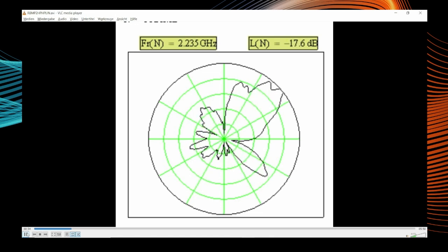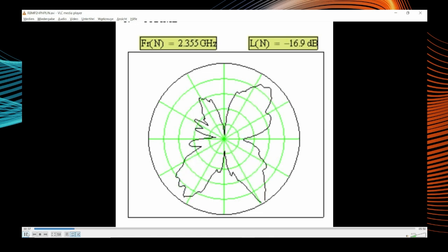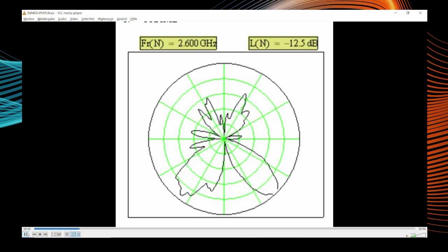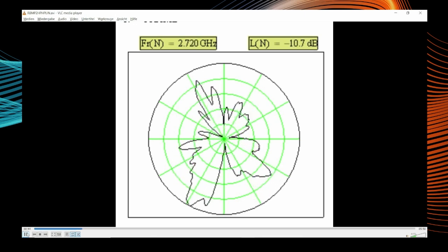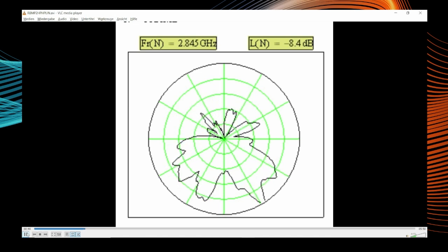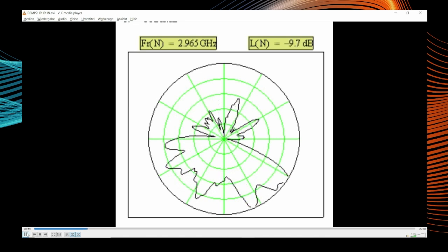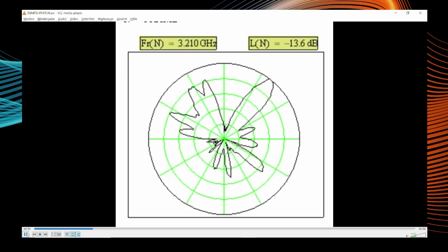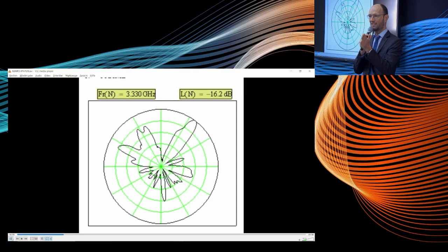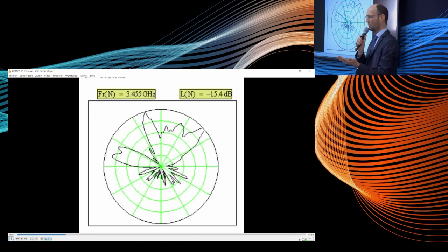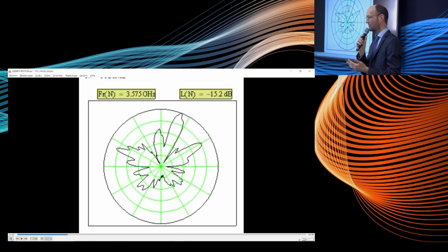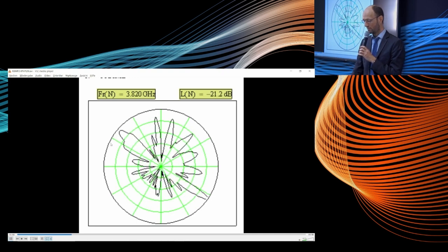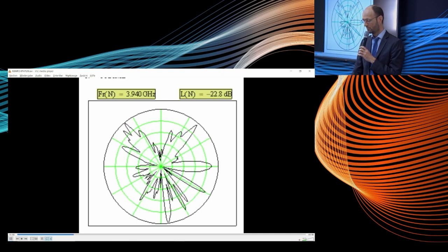And remember, what you would like to do in a semi-anechoic chamber is find this maximum radiated field strength at a certain distance, but you don't know the direction. No one knows the radiation pattern of the equipment under test. So it's really challenging to find this maximum emission and to select what step size to choose. Do you go for 90-degree steps, 30-degree steps, 10-degree steps of your turntable to always be able to capture this peak that also moves around here?